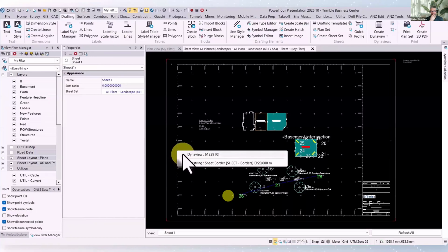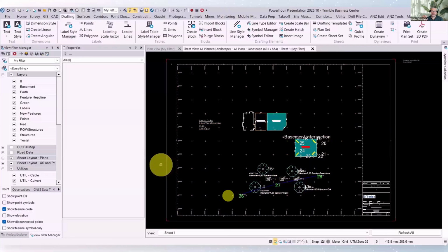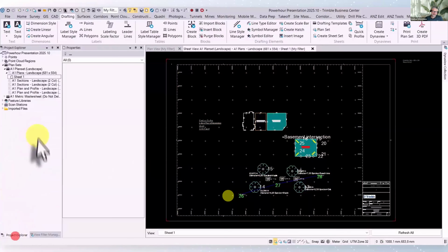And the first thing that you can do is explode the grid. Yeah, because if you do not explode the grid, it's not exported, because AutoCAD does not have this data structure of a grid. Explode it, and then it will be exported to AutoCAD.